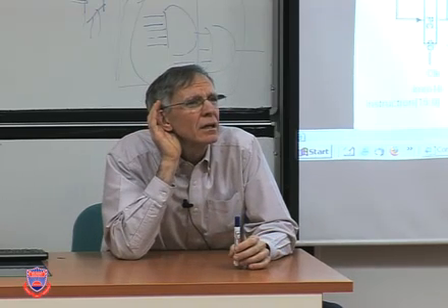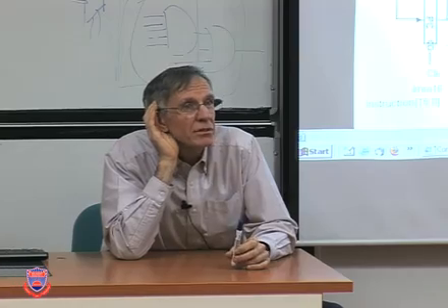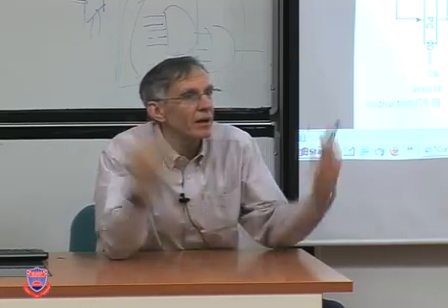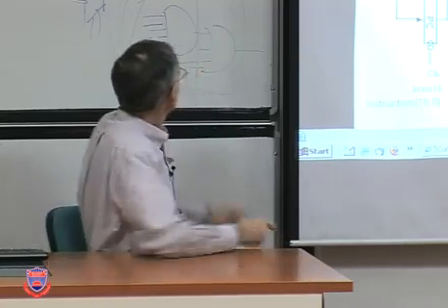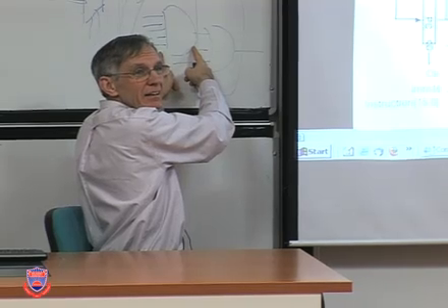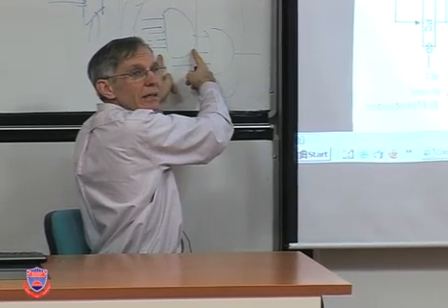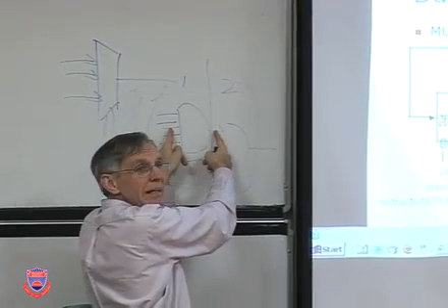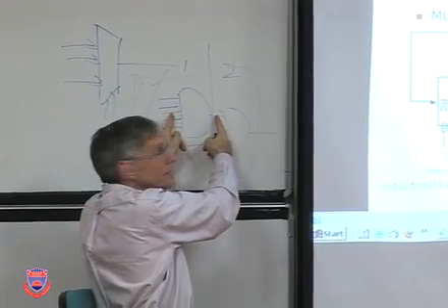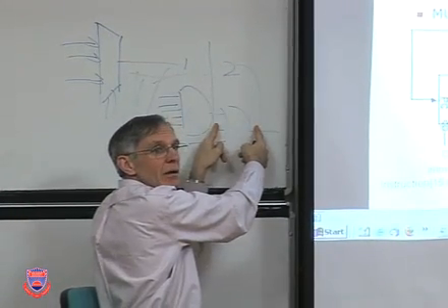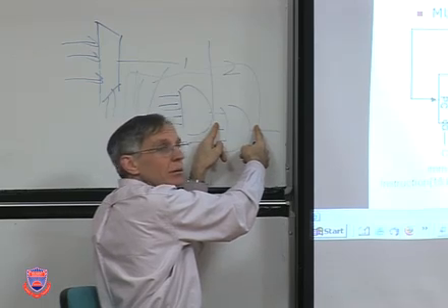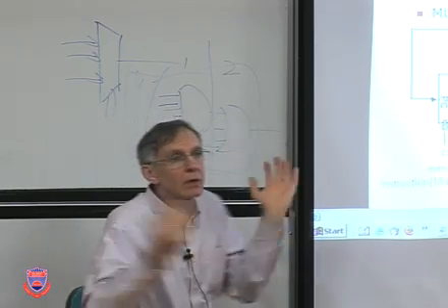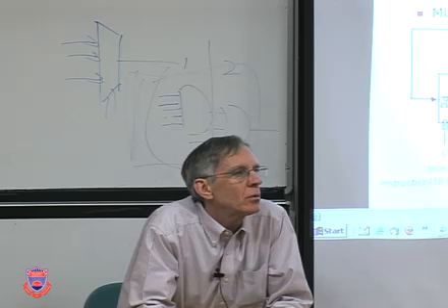Pardon? Yeah, 2 levels is faster than 3, but you didn't need to ask George Boole for that. All of us can see that. Why is it faster? Does this have a finite delay, or an infinite delay, or a 0 delay? Finite delay, right? It's non-zero. So if that's non-zero and that's non-zero, and I don't have any levels that can give 0 delay, I promise you 3 is slower than 2. We all can understand that. No, that's not what George Boole would say, though.